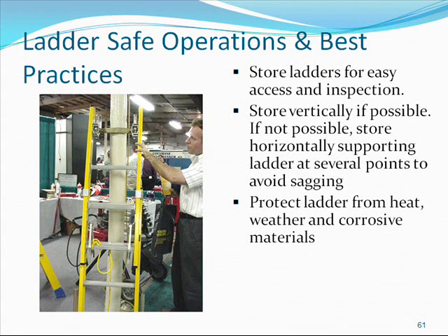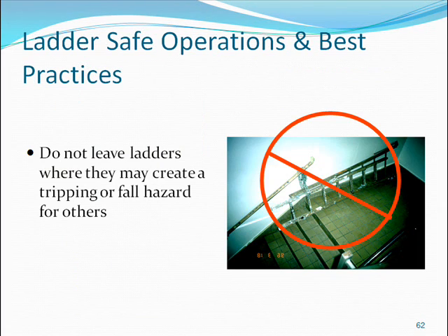Store ladders for easy access and inspection. Store vertically if possible. If not possible, store horizontally, supporting the ladder at several points to avoid sagging. Protect ladders from heat, weather, or corrosive materials. Do not leave ladders where they may create a tripping or falling hazard for others.